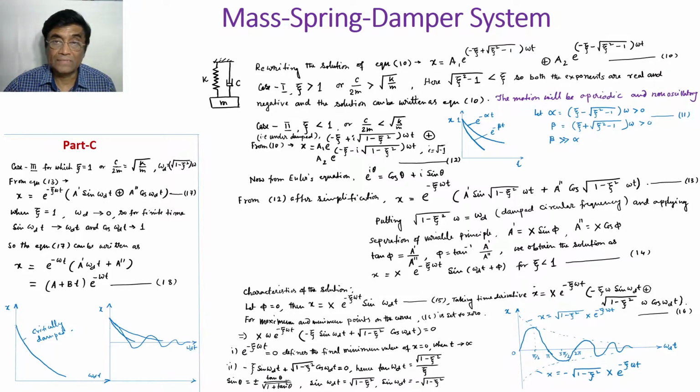And so this is called an overdamped situation. So it will be non-oscillatory in nature, and the roots will be, very interesting observation, zeta square minus 1 under the discriminant root is less than zeta. So you have a solution which is a1, some constant, e to the power minus zeta plus something which is less than minus zeta.